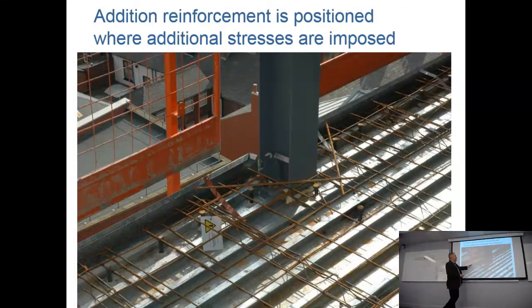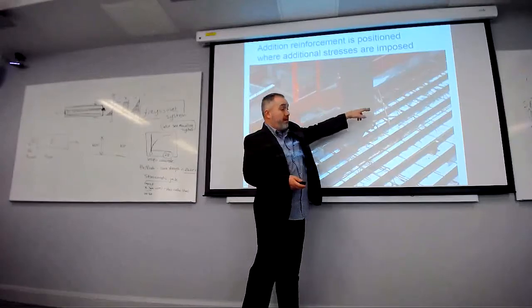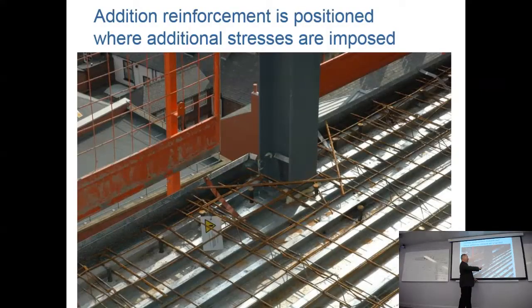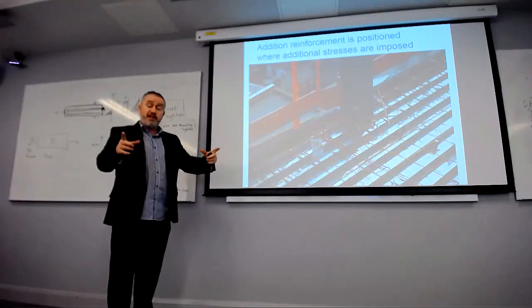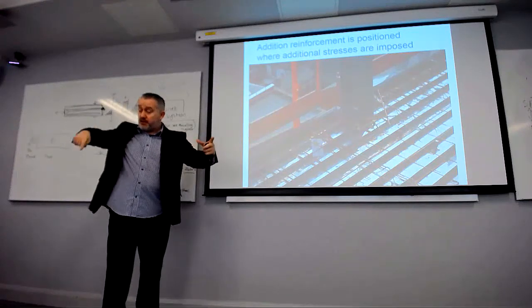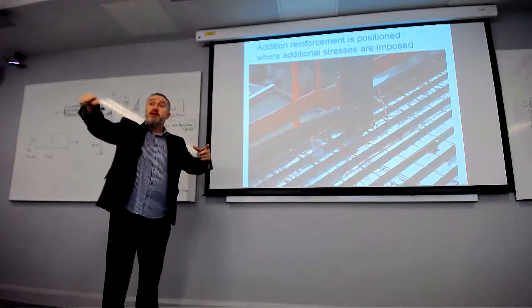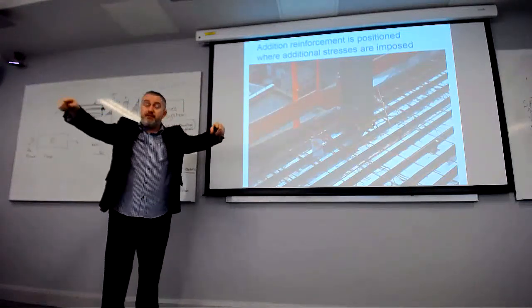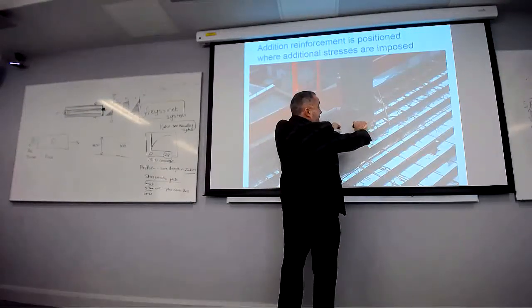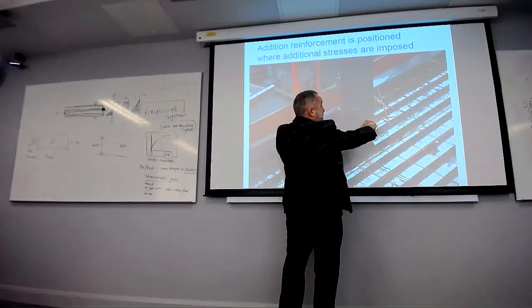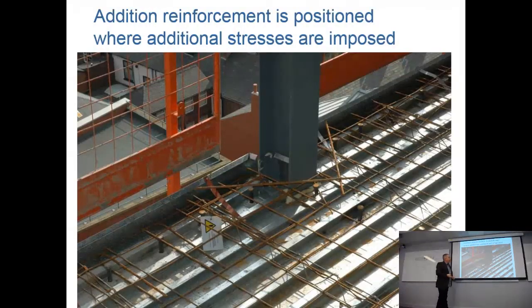and you find that whenever you have concrete going around a corner, you always have to put diagonal bars in just to stop cracks emanating from the corners. A lot of times, if you look at a manhole on the ground in concrete, quite often you get cracks coming out from the corners, because you're meant to put a reinforcement bar around to try and stop the concrete from expanding that way. And this is why these reinforcement bars are in place.